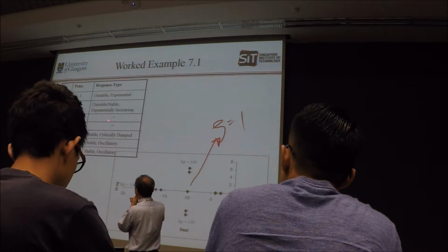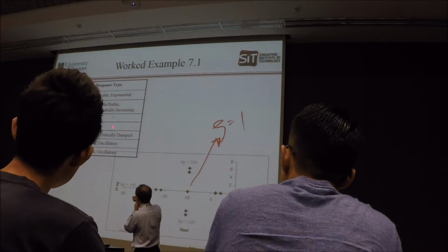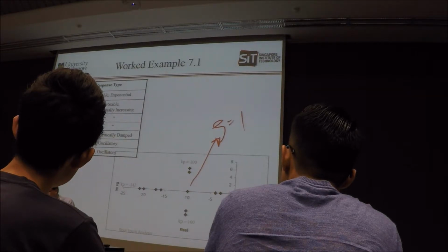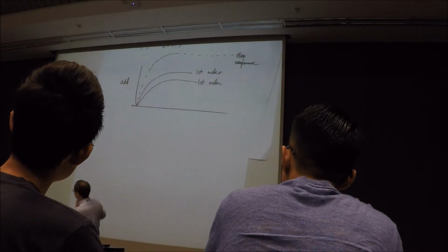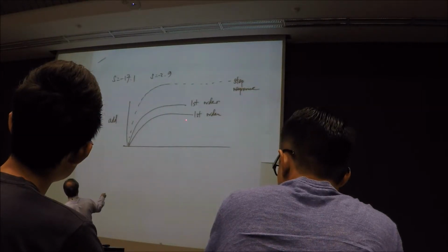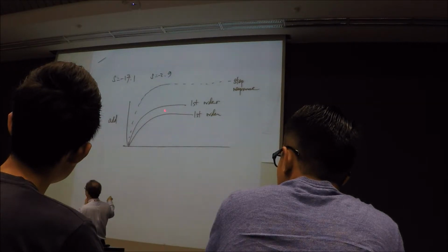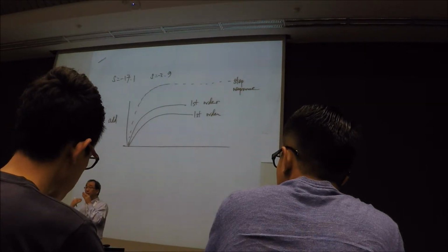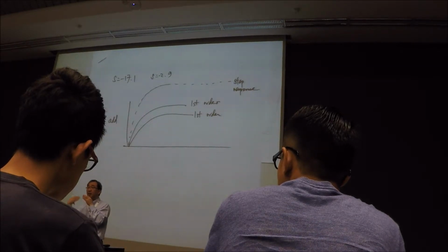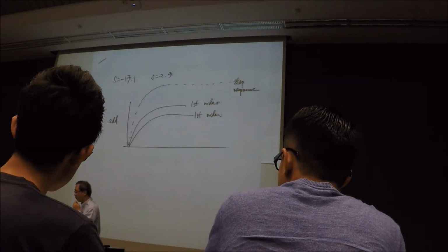So this is basically stable exponentially decreasing. But if you were to look at the actual step response, you can actually imagine, you basically have two first order responses. A first order response basically looks something like this. When you have a system characterized by two first order poles, the end result is you add the two together, and you get your final step response.